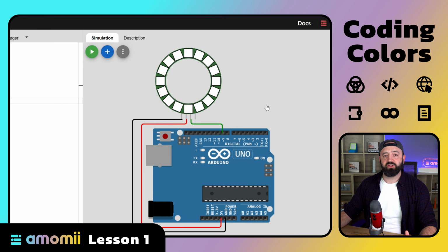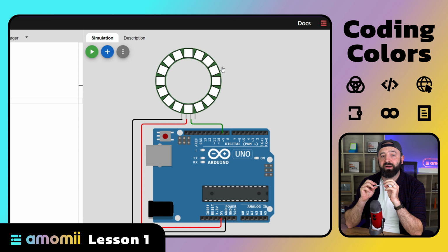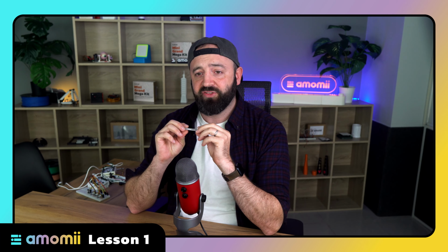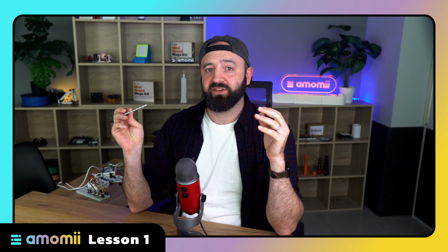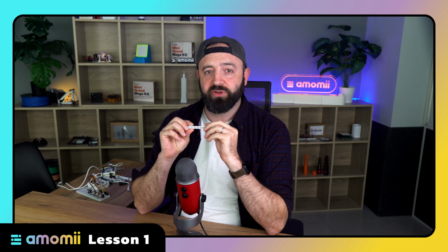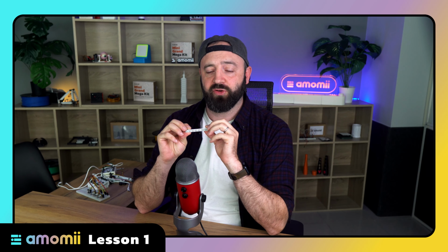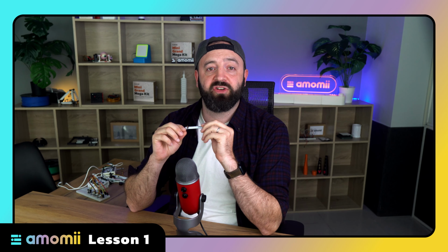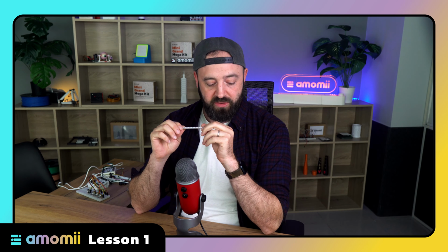But there's one thing I want you to note. This one has 16 pixels. The one that we are using is 8 pixels. This is a relatively low amount of pixels, so it should be fine to power it directly from the microcontroller. However, if you are going to try and power a lot of pixels, let's say a full strip around your bedroom, it would be advisable to use an external power source. That's because if you try to draw too much power from a microcontroller, it will shut itself down.